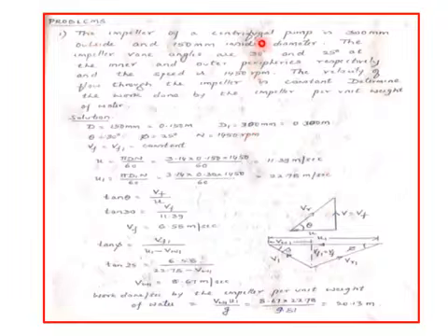Now the impeller of a centrifugal pump is 300 mm outside. Outside is always D1, and the inner circumference I represent with no suffix, that is D. So the outside diameter D1 is 300 millimeters, whereas the inside diameter is 150 millimeters, and the impeller vane angle is 30 degrees, that is theta, and the impeller vane angle is 25 degrees at the outer circumference, so that is phi.